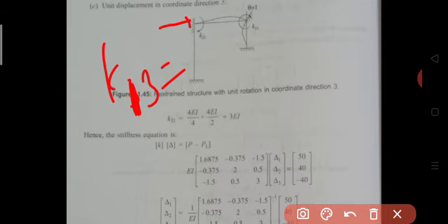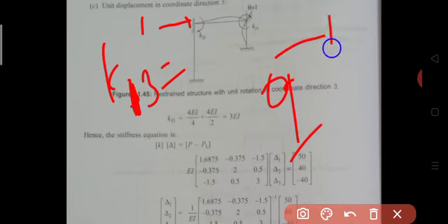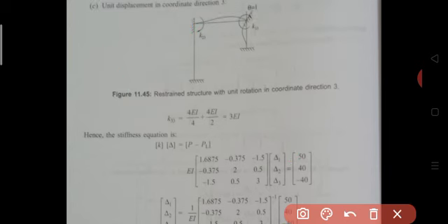It is the force coordinate direction, that is, it represents some horizontal force. With the help of these free body diagrams, we determine the horizontal reactions at joint B. For AB you get 0 horizontal reaction, for BC again 0 horizontal reaction, but for the CD portion you get one horizontal reaction. Its value is 1.5EI, in the minus x direction.